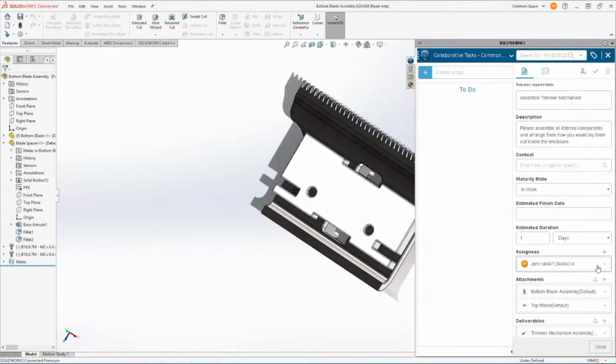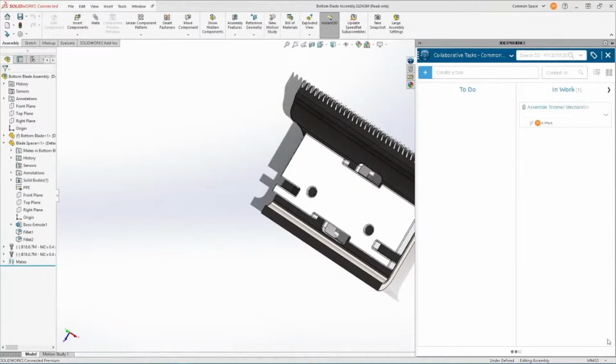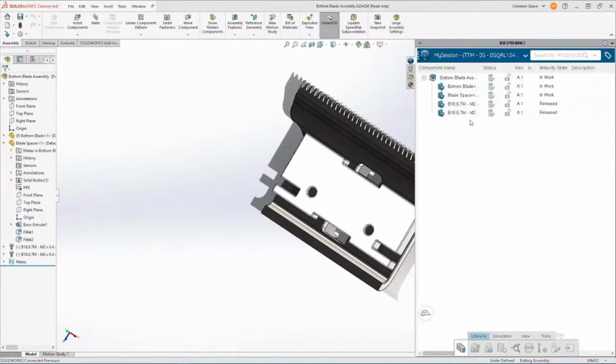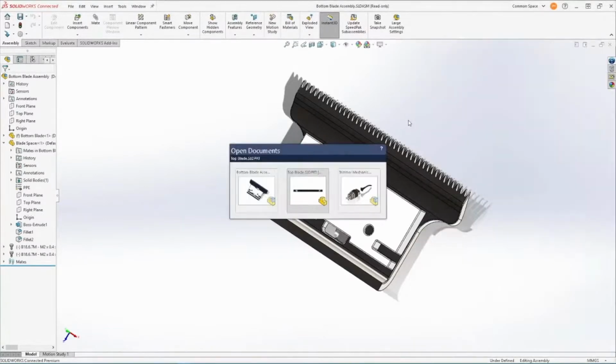And here's the first little pro tip that I'm going to throw in there. When working with multiple SOLIDWORKS files at once, we can use Control plus Tab to switch between open files. And this is similar to using the Alt-Tab shortcut in Windows. Also, as long as I hold the Control key, I can click Tab to change my selection and really just click the one that I want.